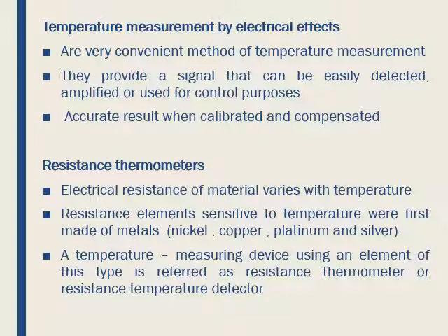Resistance thermometers, which are generally called resistance temperature detectors or RTDs. Resistance elements sensitive to temperature were first made of metals like nickel, copper, platinum and silver.